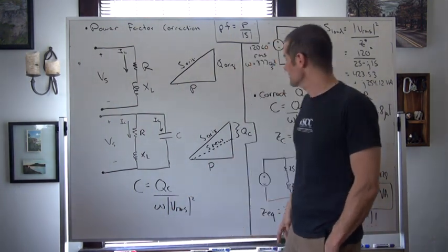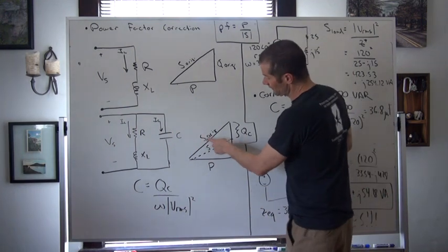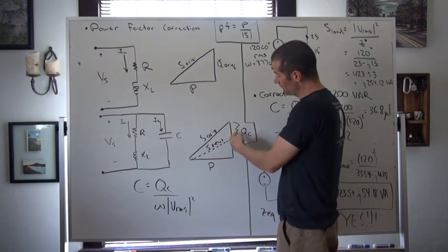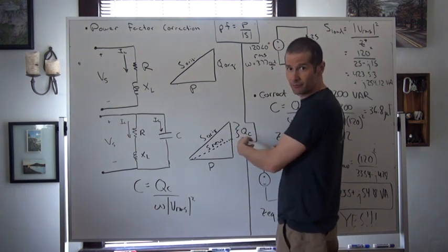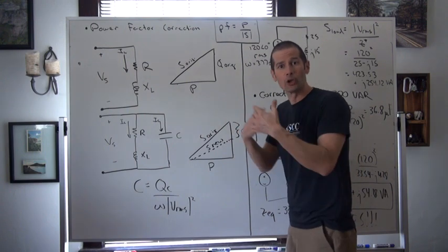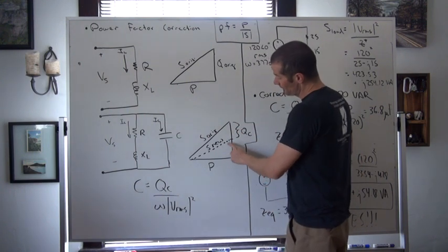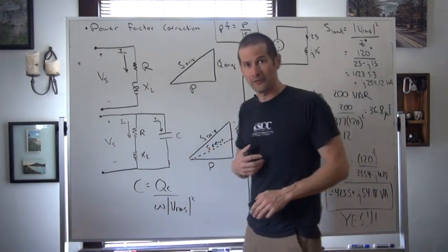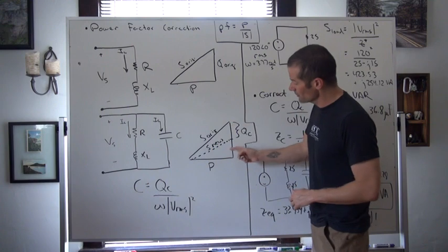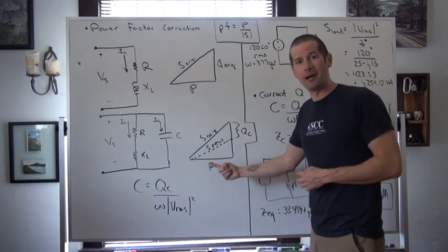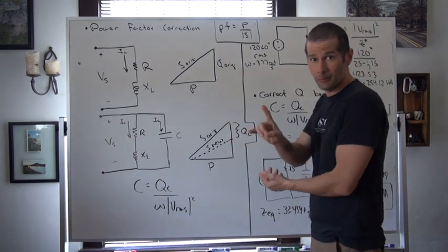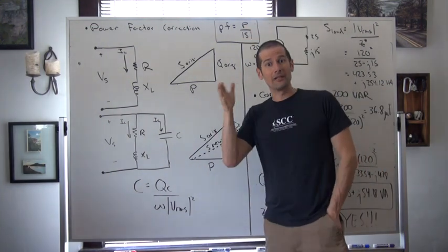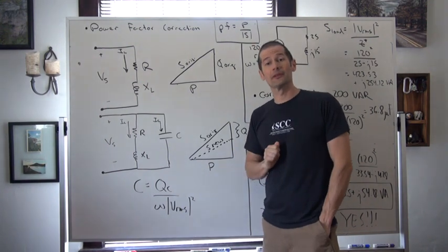So in this case, guys, what we're going to be doing is taking that original apparent power and lowering it by adding a certain amount of negative reactive power within the system, or what we call the corrected reactive power. Essentially, we create a new apparent power in the system, getting this closer and closer down towards the real power. And if you remember, the real power divided by the apparent power gives us the efficiency, or the power factor, within the system.